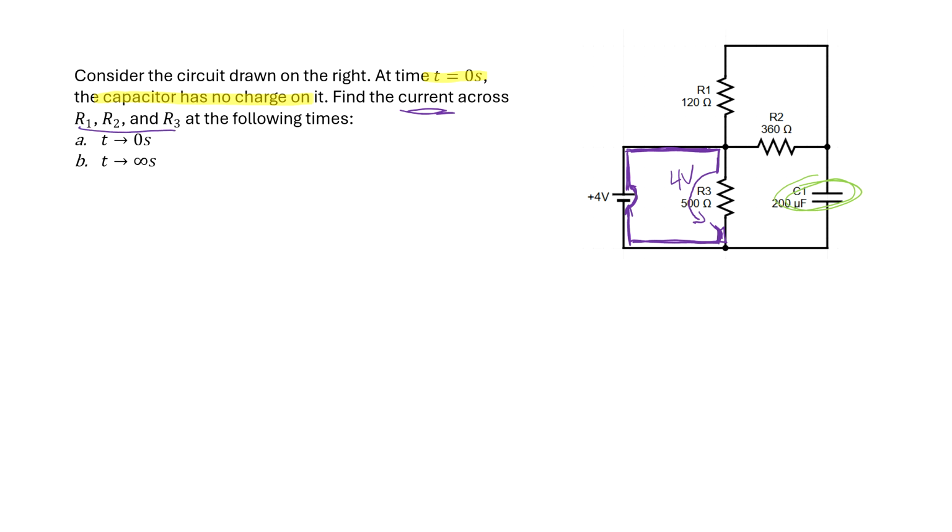And I want to remind you, each resistor is going to have its own version of Ohm's law, delta V equals IR. To get to the currents, we just have to realize that each element has its own V, I, and R, and so, delta V3 equals I3 times R3. We would then want to rearrange Ohm's law to solve for the problem.